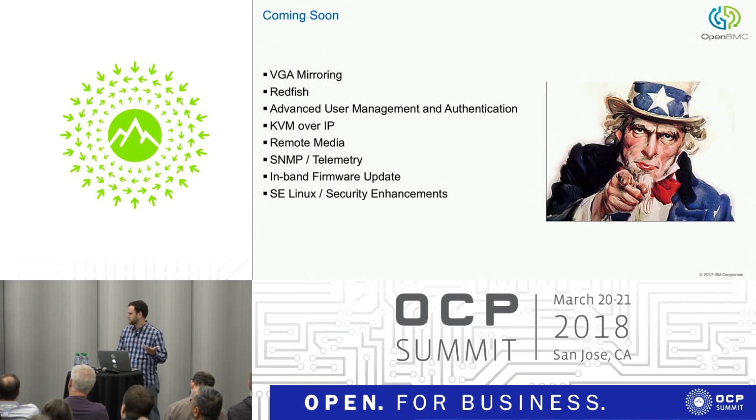And then just the security pieces. The last time we had a hackathon, a couple months ago, as an OpenBMC group, one of the things we were talking about was getting SELinux in there, getting some policies around our stuff, not running all of the applications as root. We've made a pretty strong effort to get rid of all of our Python applications out of OpenBMC. Initially, a lot of the prototyping and work that we did at the beginning, it was really easy to get together a lot of Python applications to fulfill the interfaces, but we've been slowly replacing those with C++ code and using some of the new sdbusplus functionality. So part of that security, there's not just one piece, there are a lot of little pieces that we really want to start improving on in OpenBMC.